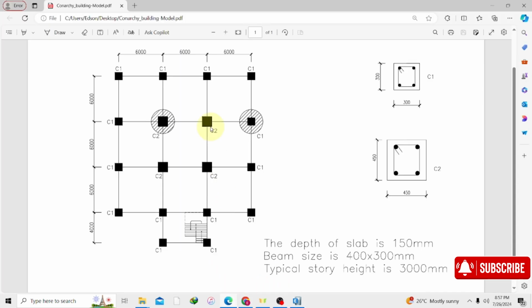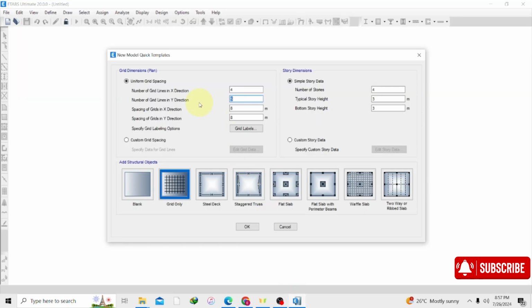So the spacing is just the dimension or the distance between our grid lines. In our x direction, we have 6,000 millimeters. That's 6 meters. And looking at this, it's quite uniform, meaning we have 6 meters throughout. So 6 meters, 6 meters, 6 meters. So in our spacing of grids in x direction, we are going to input 6 because our units are in meters. But if it was supposed to be in millimeters here, we will just input 6,000.